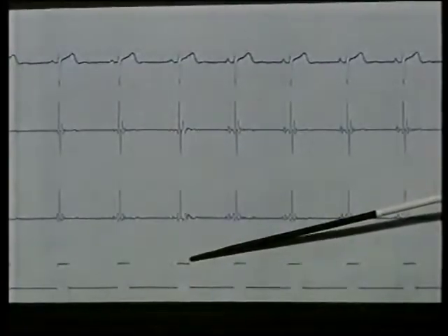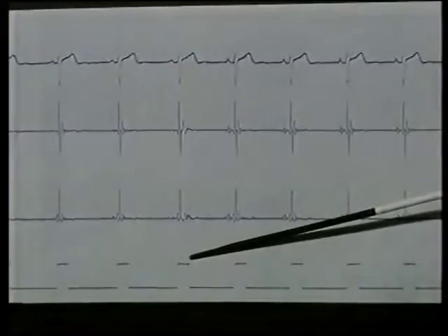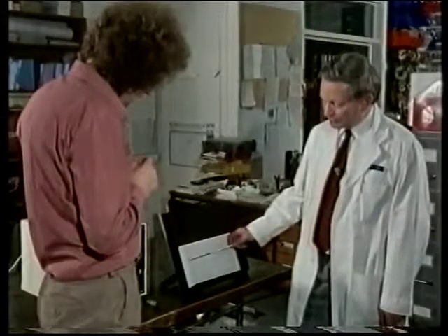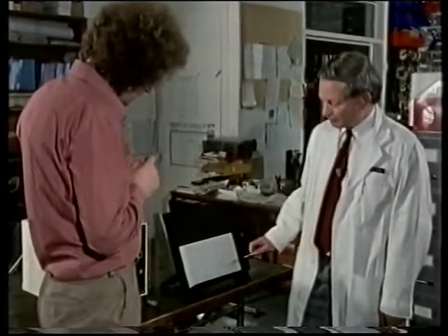And this also has the very useful effect that during the time the pulse is there, the monostable is dead, so that if there is any other spike waveform derived from the high-pass filtering of the original signal, it doesn't fire very rapidly straight after the first time.